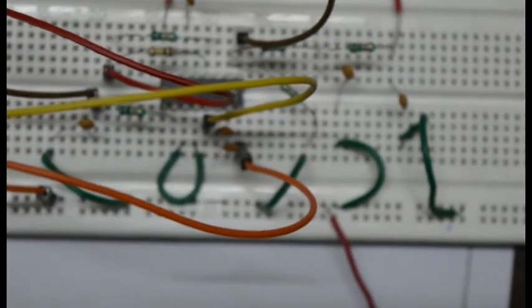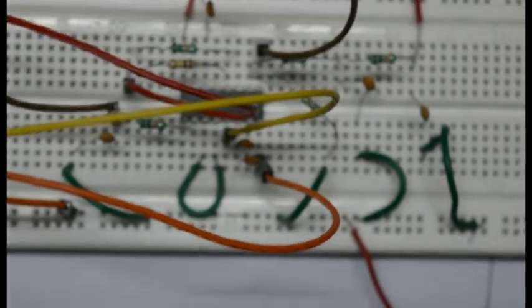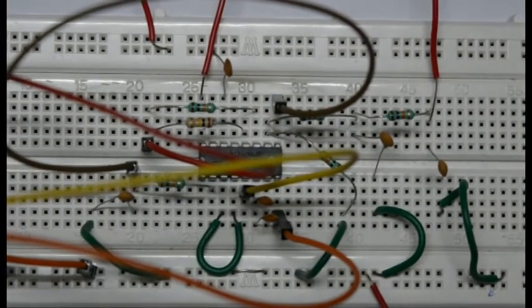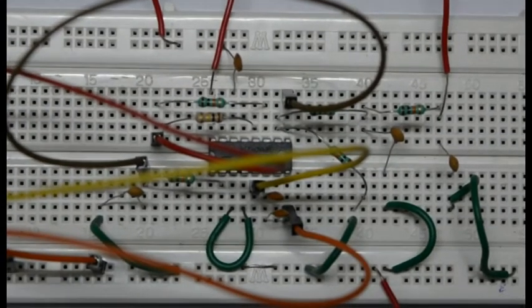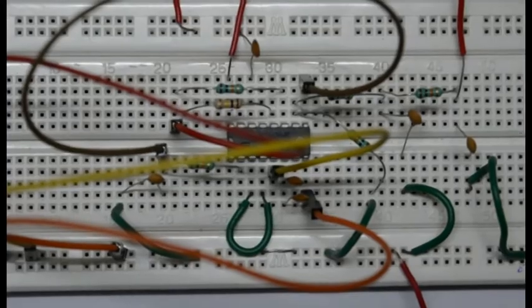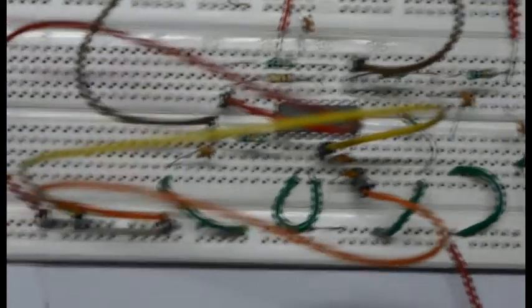Now we have to design our circuit. As our input FM signal carrier frequency is 27 kHz, we have to design our circuit, that is choose our components in such a way that the output frequency of the VCO of the IC should be nearly equal to 27 kHz, so that the PLL takes less time to lock the input frequency and VCO output frequency.